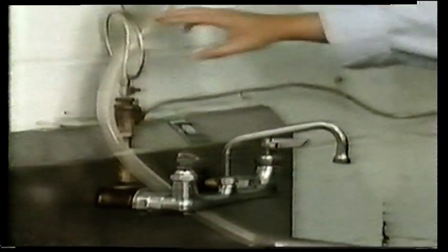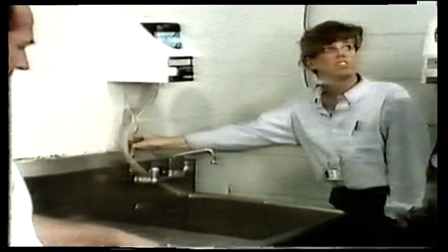The survey team found one of the hospital kitchen sinks with soap injection incorrectly installed. Questioning by the survey team established that this type of installation by an outside vendor was an ongoing problem encountered by hospital facility services. The survey team will recommend the installation of an atmospheric vacuum breaker and the relocation of the soap injector. Atmospheric vacuum breakers must be installed higher than the actual water outlets and in accordance with plumbing regulations. The survey team also examines every slop sink.